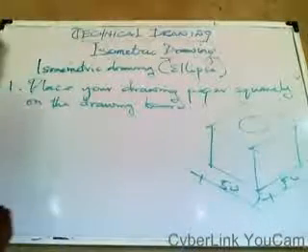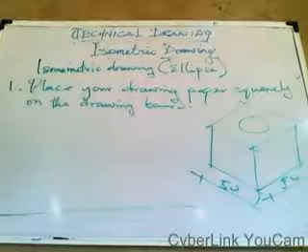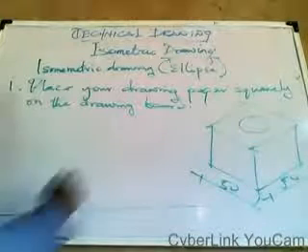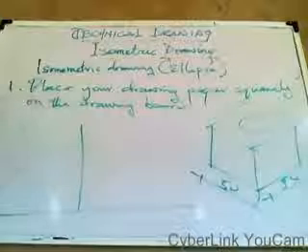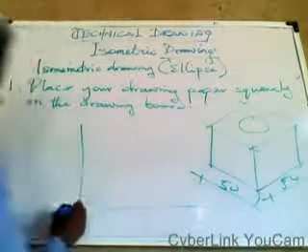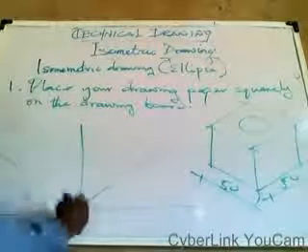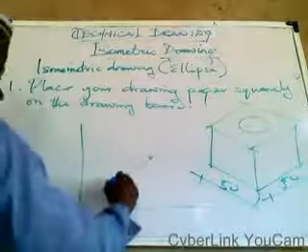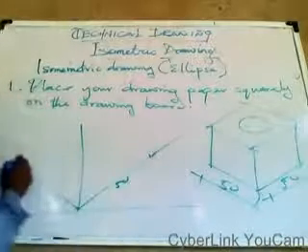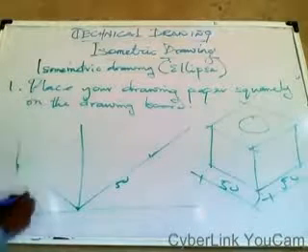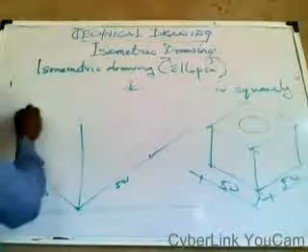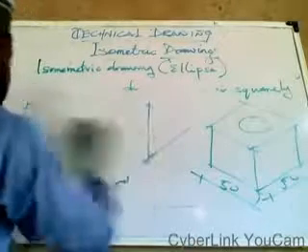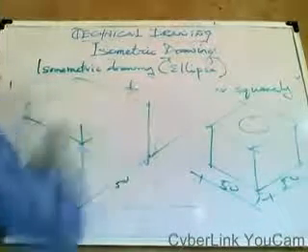The first thing is to draw your horizontal line. You want to start now. After drawing the horizontal line, this vertical line, you draw it with the aid of your T-square and your set square. Then you draw the receding lines like this. And from here to here, you measure your 50. Let this one continue. Let's say this one is your 50. Draw this one like this, and this one like this.